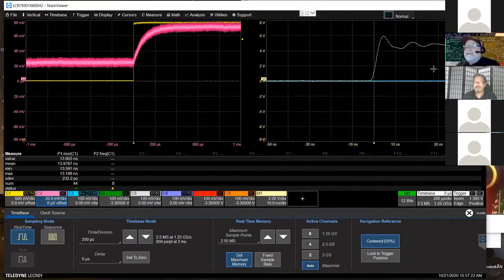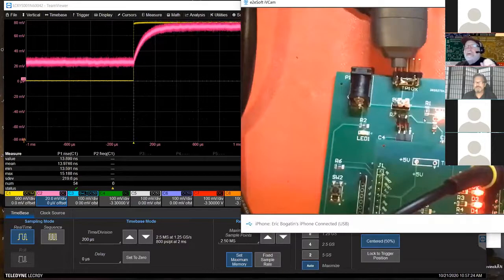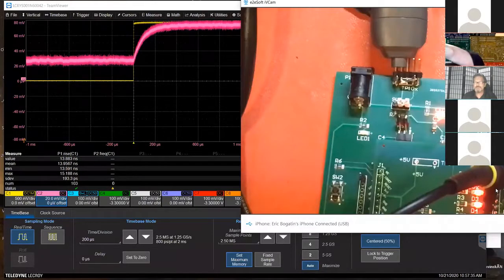How come? This is where, again, we're opening up a new window into what's going on with our board, to understand how that board is actually working. It's because of all of those decoupling capacitors that we have locally where the I/O are switching.